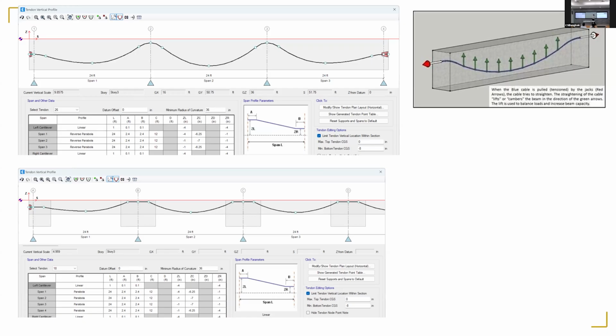So now the challenge is that this post-tensioning should be done in such a way that you don't overlift the slab. If you overlift the slab, tension will develop at the top and everything will break and crack. Because if you provide over post-tensioning and you push it, and the dead load is not there to balance it, the slab will lift upwards and crack and break. And it has happened. So post-tensioning is to be designed in a very sweet spot, not so much that it causes uplift and tension at the top, not so little that it causes tension at the bottom from the load. So it has to be just perfect.